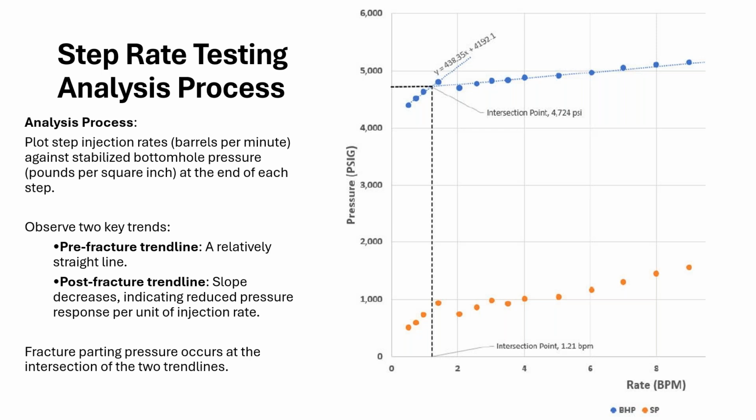Okay. I think this will be the last one. This is kind of a follow-up question. They're asking, what lithology are those formations that require higher pressures to inject into? I would say generally increasingly shaly sandstones. You're targeting sandstones when you're looking for a good formation to inject into. But as those progress into shaly, you'll start to see less and less permeability.